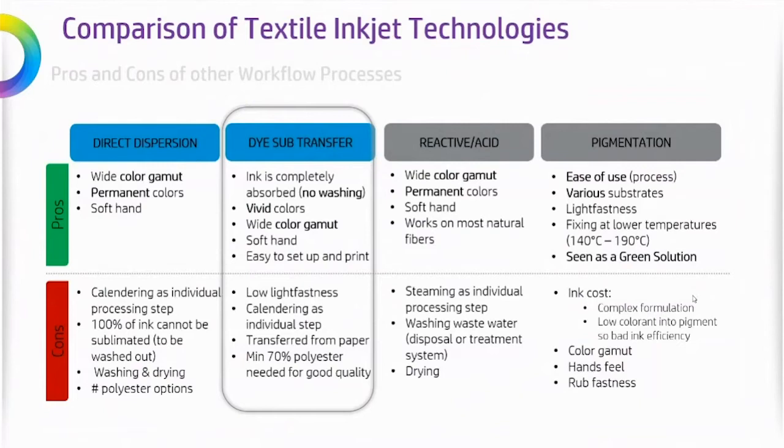Calendar as an individual step. Now with dye sub printing, it's not really a print-and-done type process. What I call part of the printing process is the calendaring. So you have to calendar these prints for it to be done. A lot of people look at that as a con, as it is another step to printing. For me, I've been in dye sub going on 13 years. That's really not a con for me. I'm used to it. So I guess it depends on where you're at in your process, if you're starting out in dye sub or if you're used to dye sub.